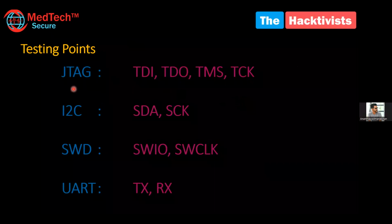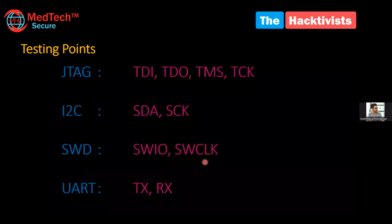If it is using a JTAG interface, we have to find these 4 points in that device to find out what communication is happening. If it is using I2C, we have to find SDA and SCL. For the SWD protocol, SWDIO and SWCLK need to be found. And for UART, as we looked at initially, we have to find the transmitter and receiver points. These are the testing points for these protocols.